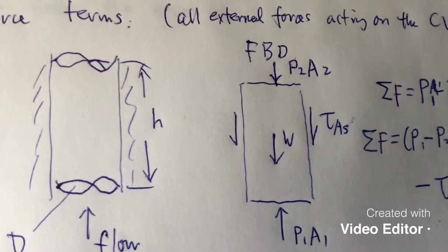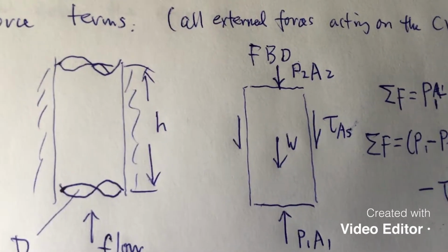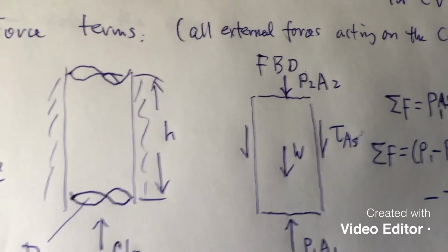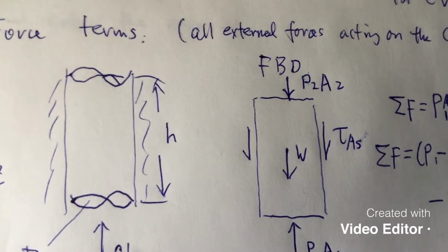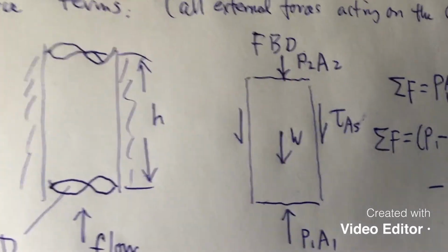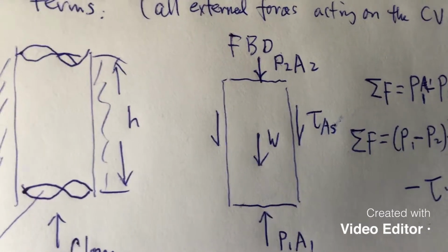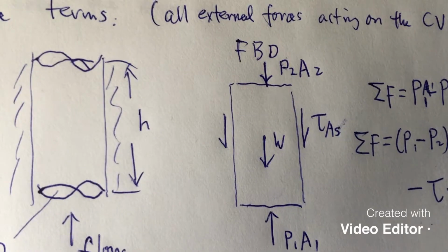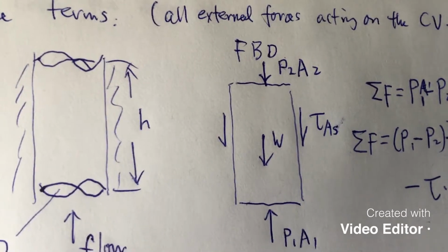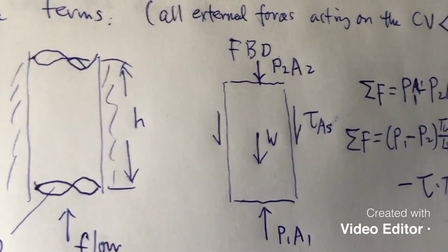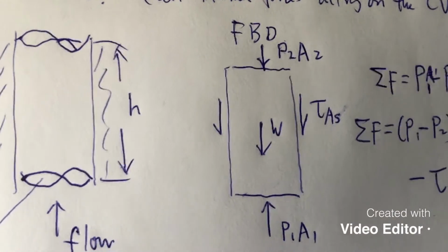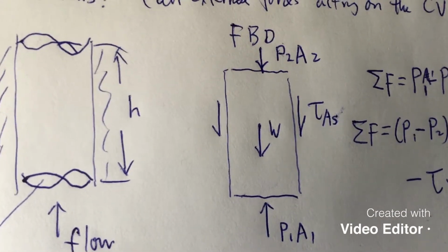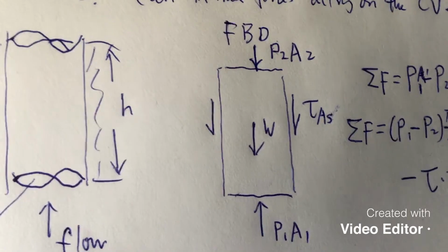It doesn't matter the orientation of your face, you always feel the pressure push into your face, right? So the pressure forces always go towards the surface. Be careful, it doesn't matter the flow direction. Very important. You need to know how to draw the direction of the pressure force, right?